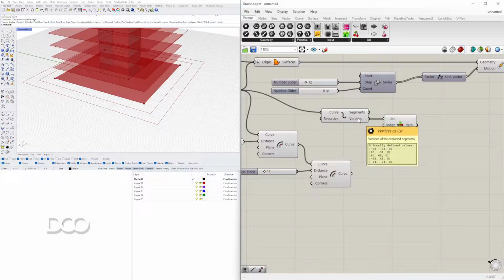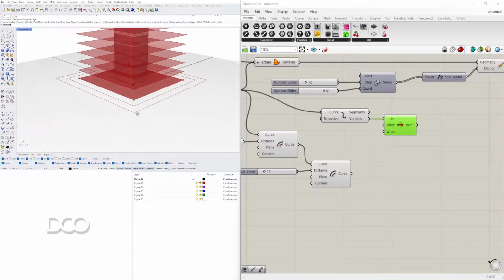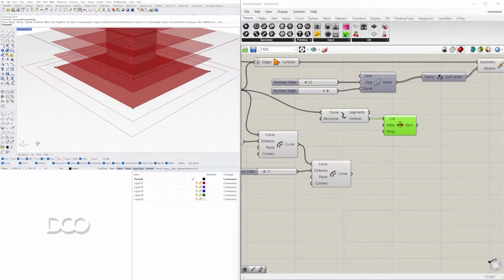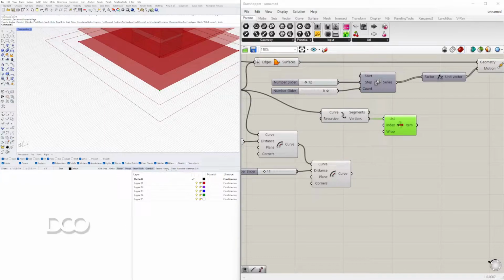And when I hover here, it says 5 points. And here we only have 1 point. We need this point to then move it in the negative Y direction. And I use this widget here inside of Rhino to guide myself as to which way I want to extrude. So we'll take or move something.